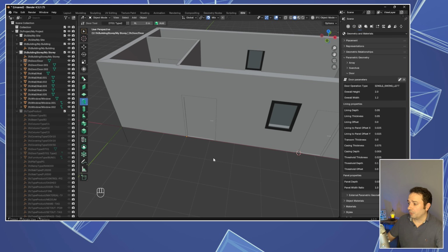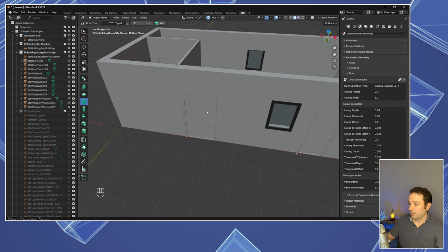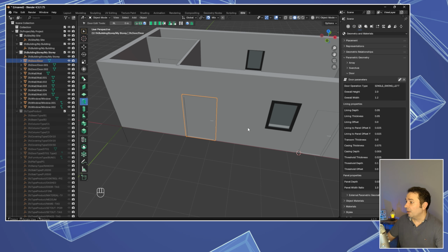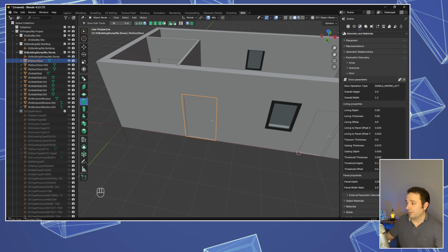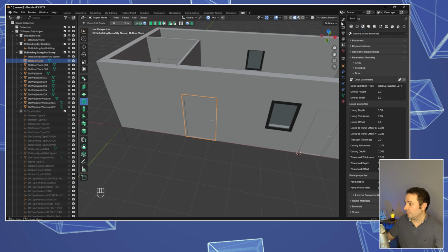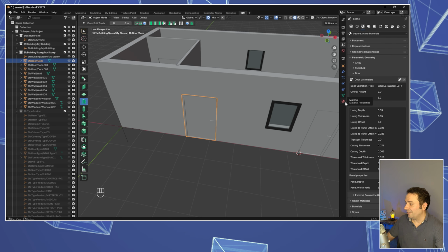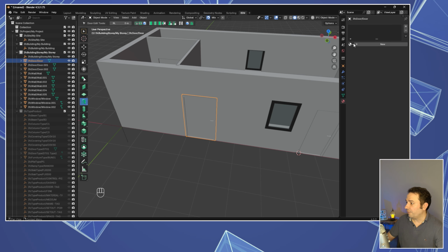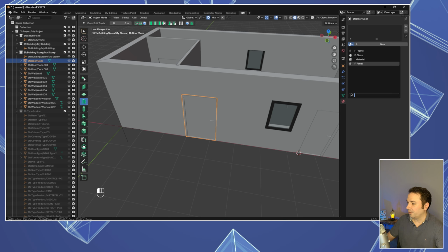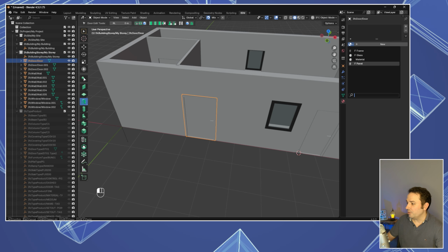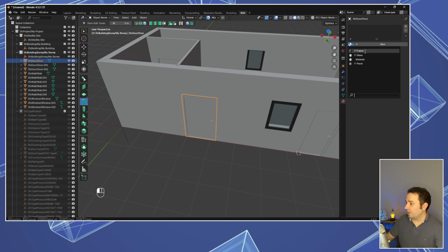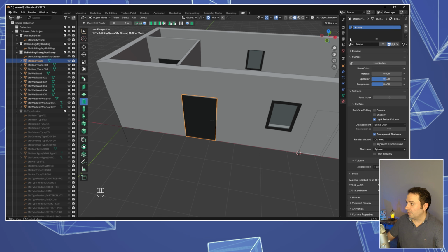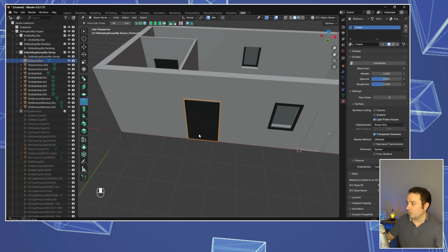Another thing you can quickly do is change the visualization of this door. I found gray on gray pretty annoying, to be honest. I'm gonna show you my personal trick. You can go here to the material property in Blender of this element. You can see that now nothing is there. If we go here, you can see that we have the materials that were used for the door. So we can add frame, and you can see all of a sudden the door changing color.